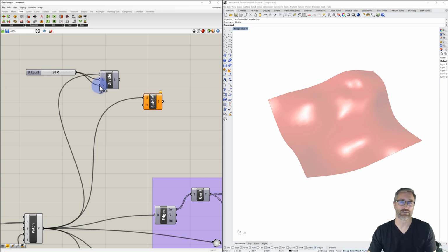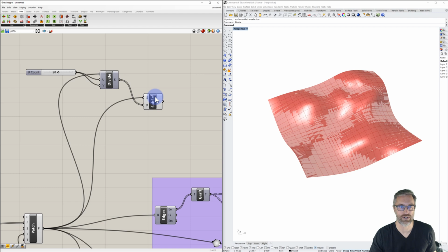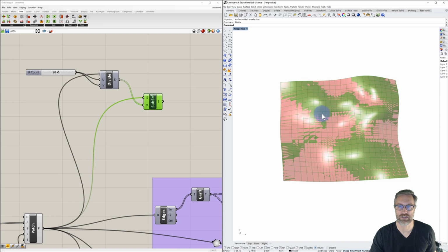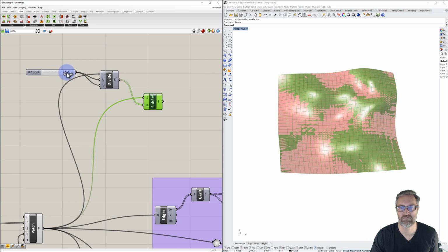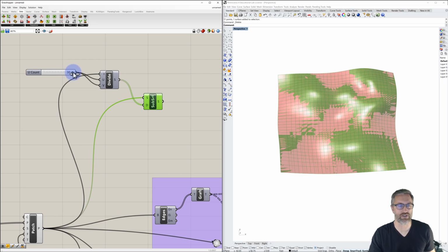This goes back to the earlier reading that we had. This is a NURBS calculus surface, and so that's why you get U and V traveling across that surface as opposed to X, Y, and Z, which are Cartesian coordinates. So we take this divide, we plug it into our surface, and now we can see we get this smaller grid on there. And so if we want to increase those, we can. If we want to decrease it, we can turn it down. So there's a high enough resolution of our surface patches there.